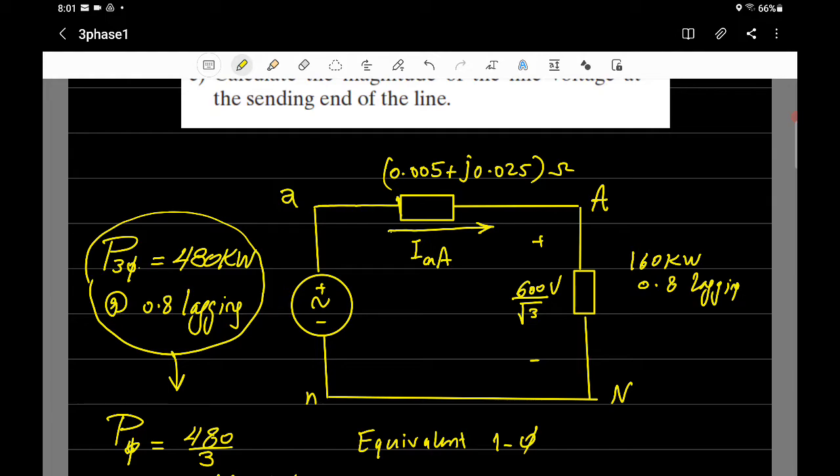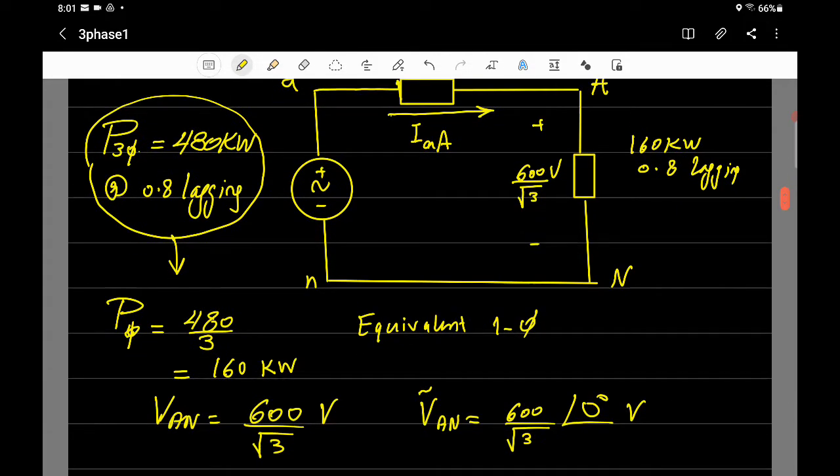How do you calculate it? Well, remember, for current there are many relationships. You've got to think about it, because if you have this question, how do you answer it? Well, current can be calculated if you know the voltage and the impedance, right? But you don't know the impedance here. Z is not given. So it's not going to work. What other relationship? There is a relationship between the complex power S and the current.